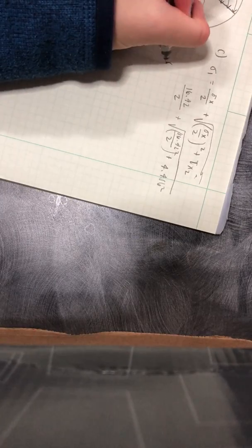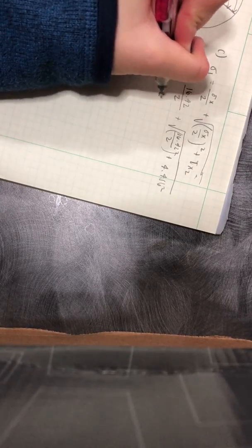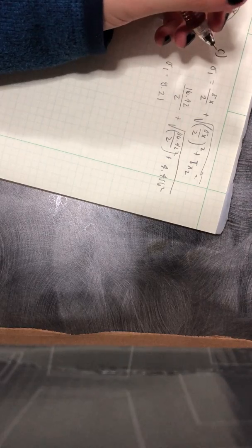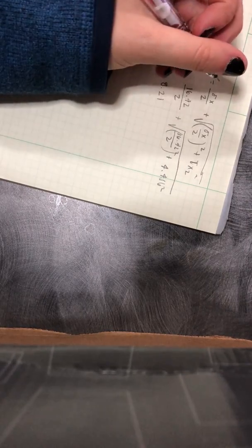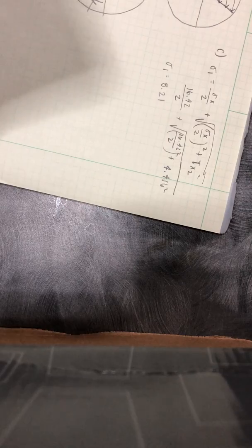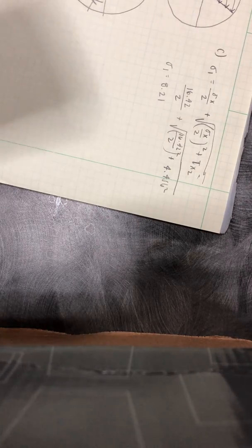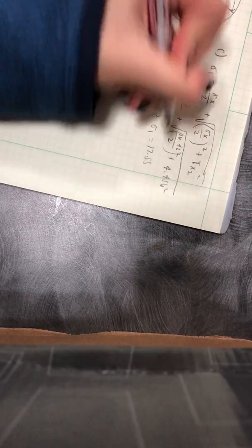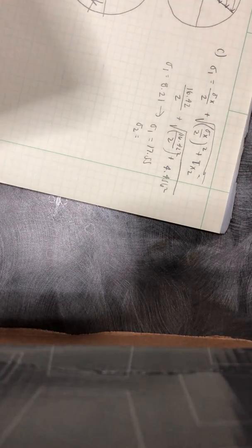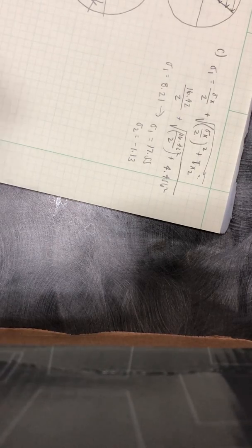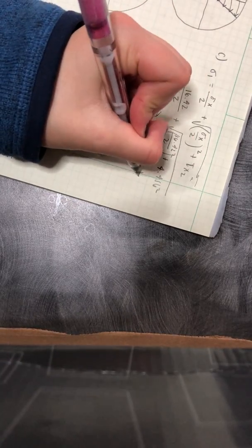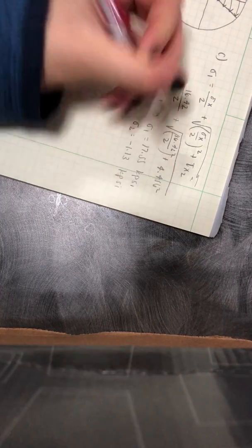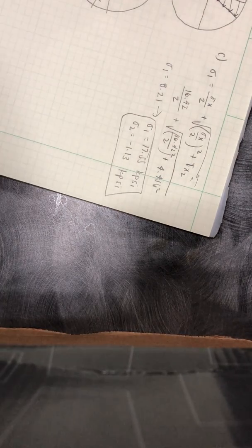we're going to get for stress 1, 8.21, and then plus, so that's the B, so 8.21 plus 9.34 is going to turn into, so stress 1 is 17.55, and stress 2 is going to be negative 1.13. So that's what we have there. So that's going to be kpsi and kpsi. So those are going to be our answers for that.